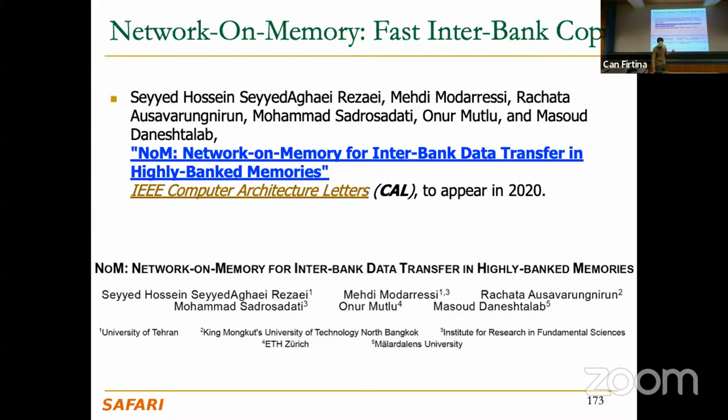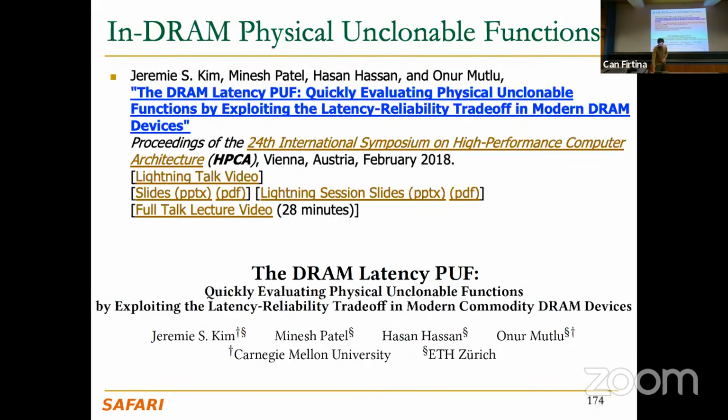Some of these works, we will cover in more detail. I think that next week, after we go step by step over the key important works here, you will also understand much faster the details of other works as well. And inside DRAM, we can also somehow compute, not only with the Ambit idea, with the majority functions, but you can also create data that is useful.